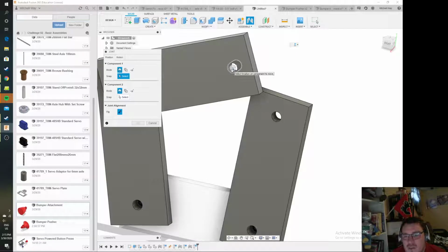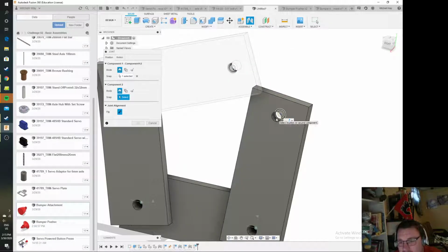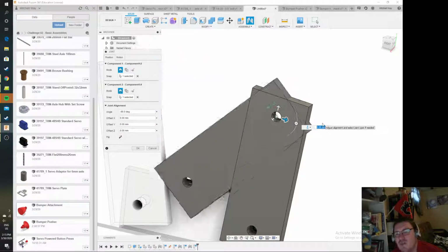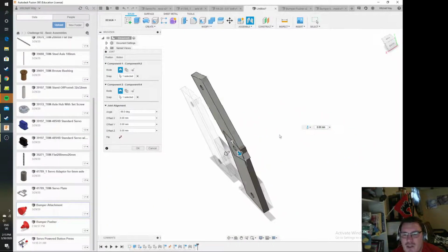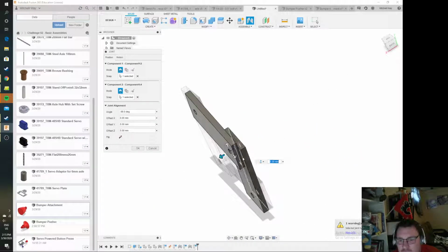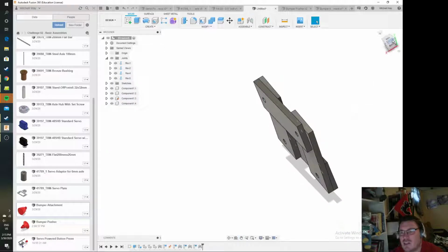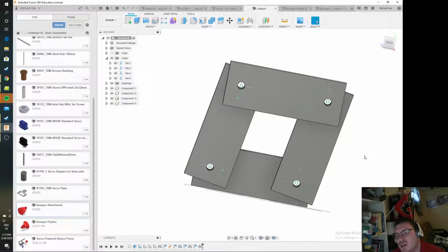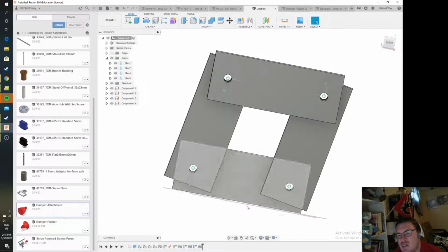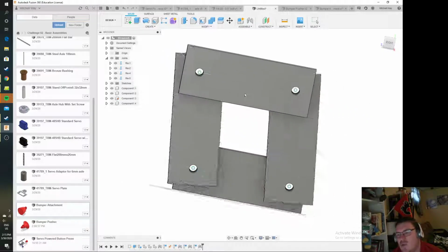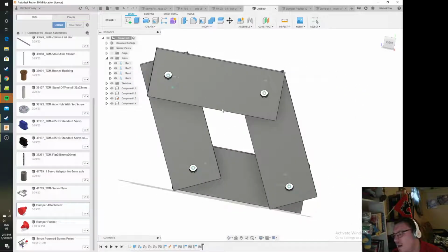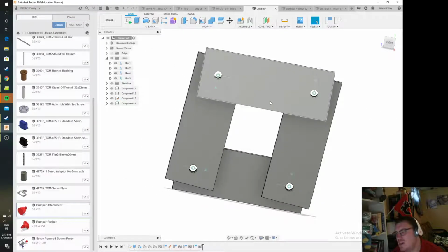Now, for those of you playing along at home, you might realize that this particular setup, if I set it up just right, is going to create a really interesting puzzle. Because now that I've connected all 4 of those pieces, and I know that this bottom piece here is grounded, that means that if I move this, categorically the other pieces of this drawing have to move with it. So we've in essence created that same motion link by just attaching things together. We don't necessarily have to put that motion link into place.